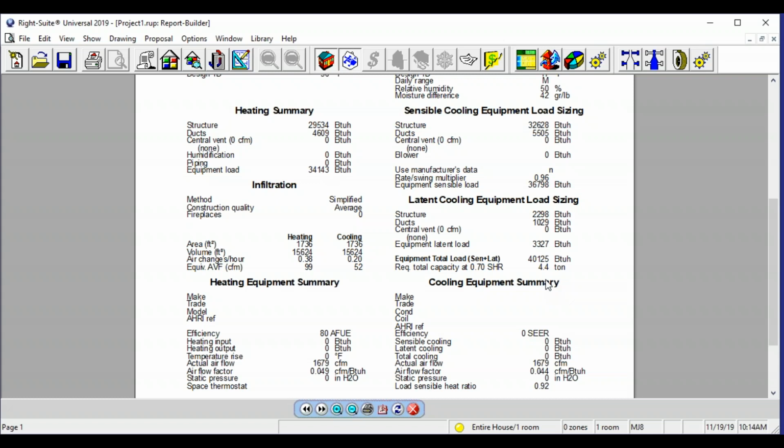Now with this though, like I said, some areas have different codes in effect, and you might need to use the other way with sensible heat ratio, but I don't recommend it. But it's definitely not an area that tells you the tonnage of the unit. That is 100% not a true area that effectively tells you the tonnage that you need for this house. Just by looking at this, in my experience, most likely a 3.5 ton. Not 100% on a 3.5 ton though.